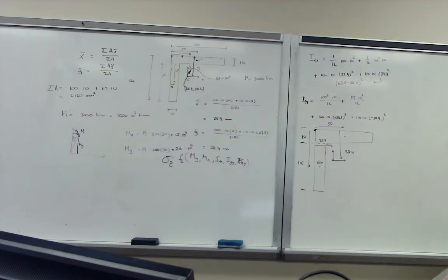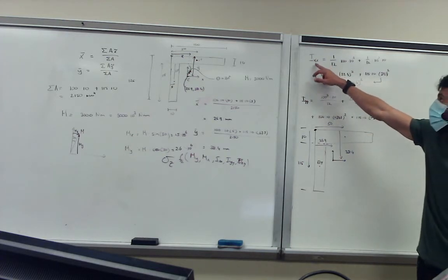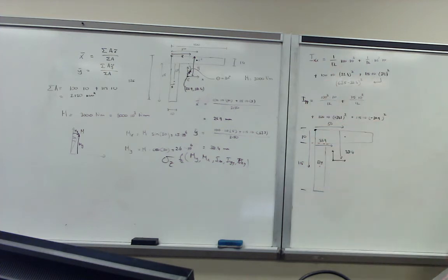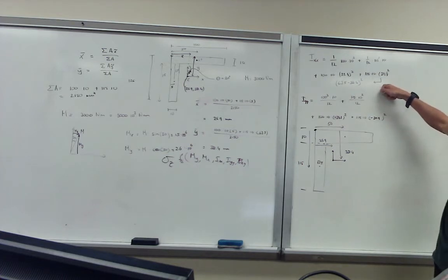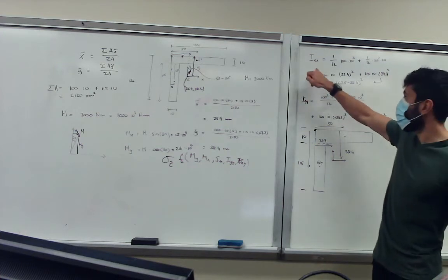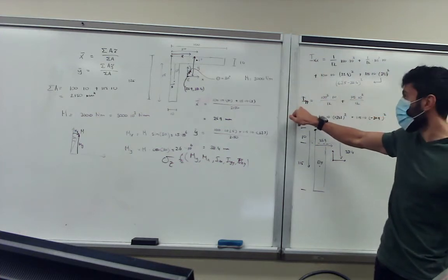Sorry, not reference axis. So where did the 67.5 come from? That's because we are looking at it based on a reference point, in IXX, if we're taking it with respect to X. It should be the central moment of inertia around your x-axis, so you basically take the y distance. But in the 20.9, we took the x distance. Did we? We did the 50 minus. Basically this one around x, you take the y distance; this one around y, you take the x distance.